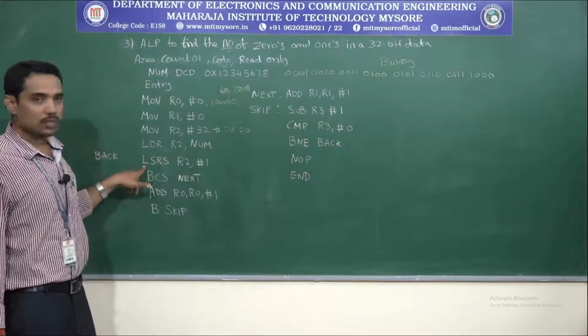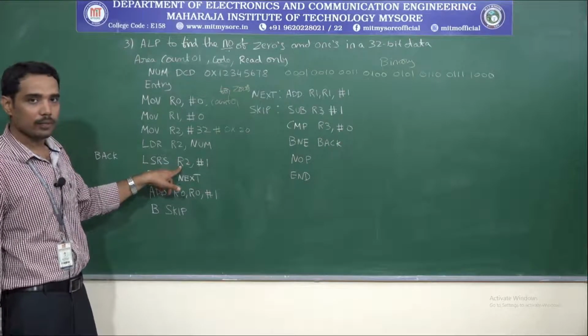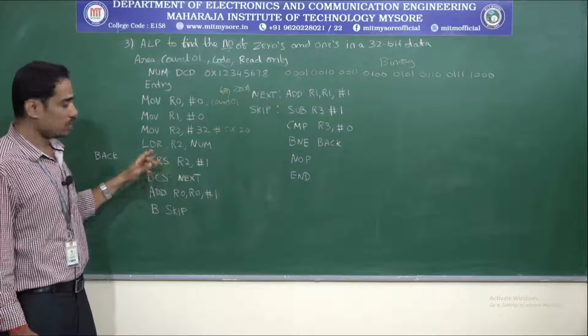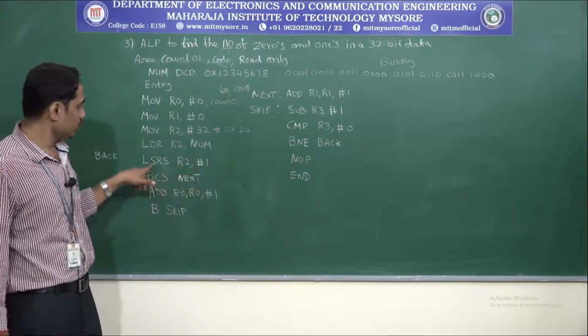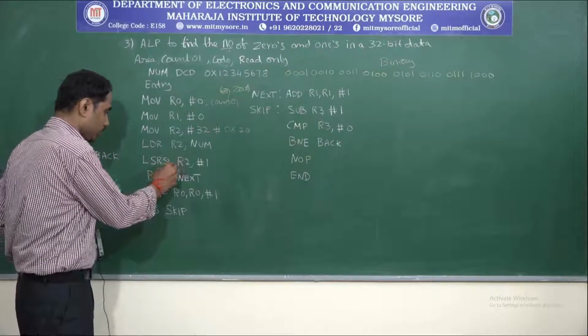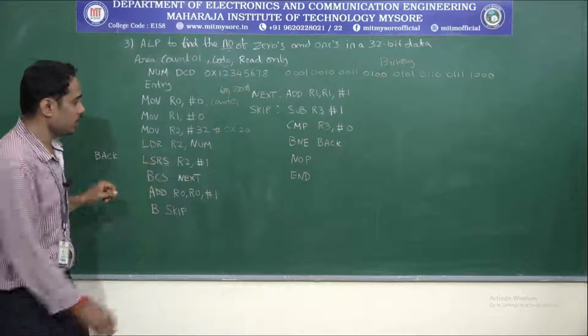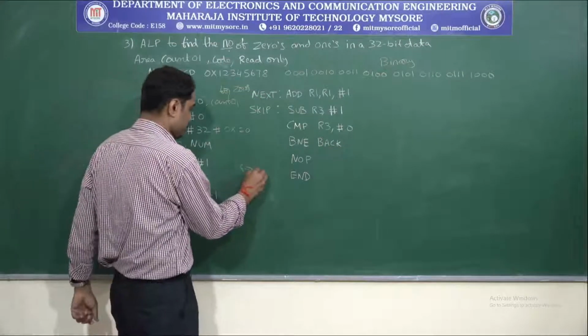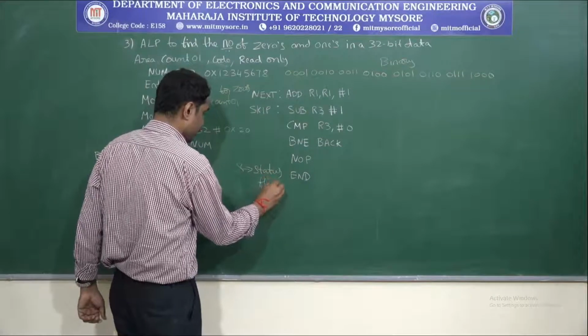And then using the logical shift right instruction, we are going to shift the data towards right by 1 position. And the term LSRS, logical shift right, S here implies status flag.